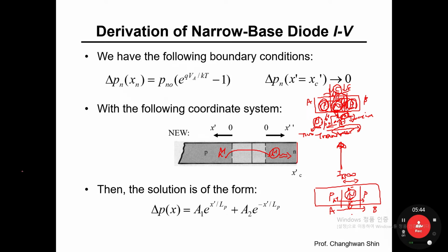Previously, when analyzing a single PN junction diode, holes are injected into the N side and diffuse out. While diffusing out, they recombine with many electrons in the N side. So in the end, all the holes are recombined with electrons, and no holes are left at x of xn, which I would say is x of infinity.